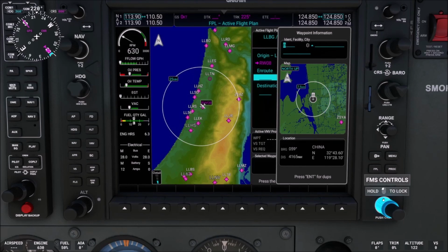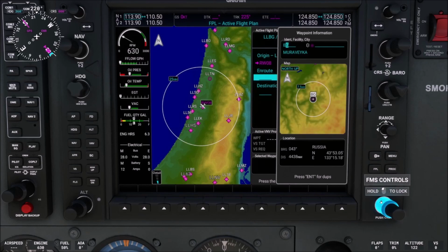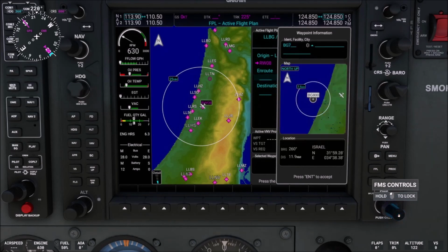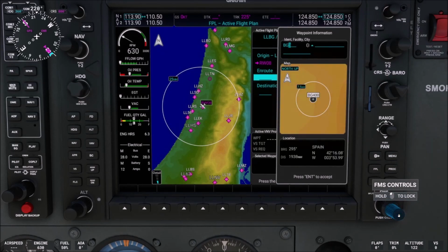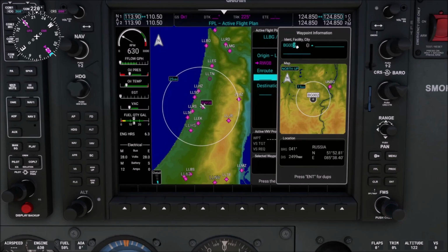Inner knob, the big knob, next position. Outer knob, the small knob, G. Okay, we continue. Inner knob, next position, 0. No, not from this direction. A, B, C. We scroll down. It will be faster. Next position 0, exactly. And next position is 2. Now we scroll up. Okay. 0, 0, 2.